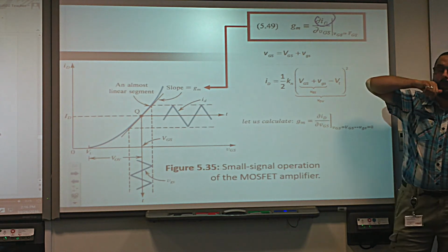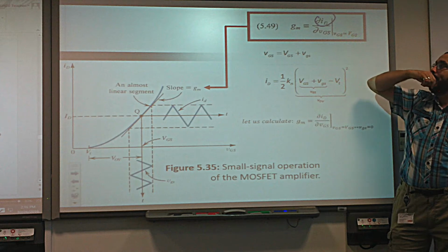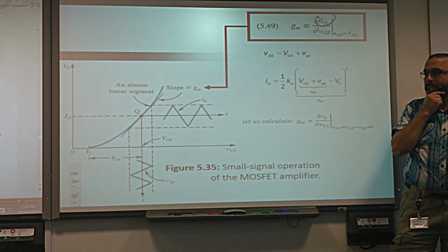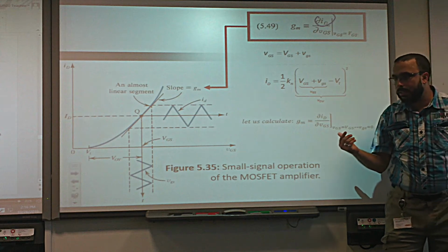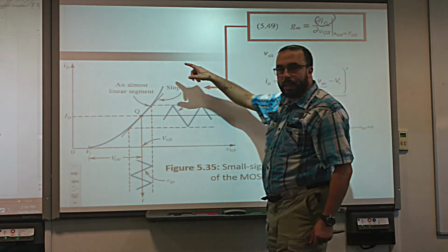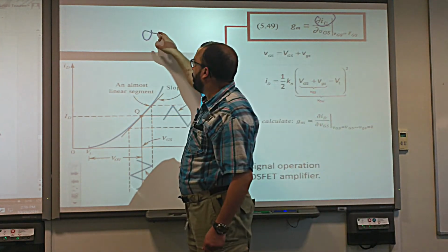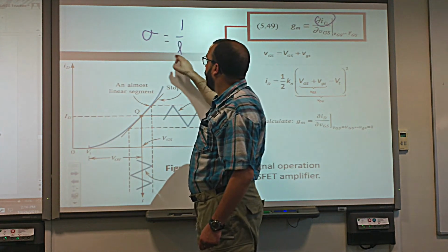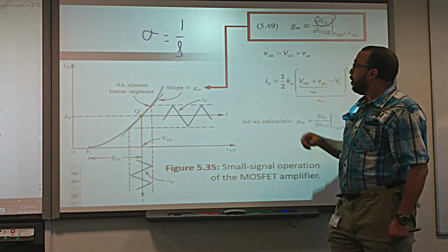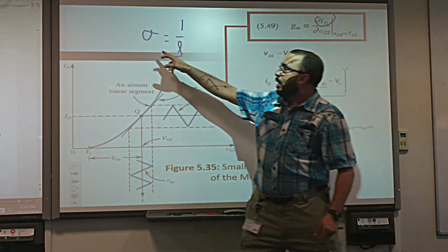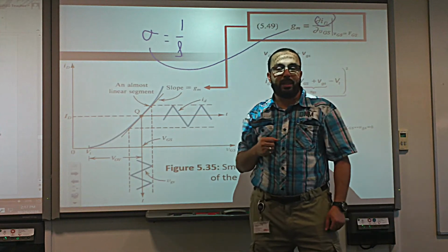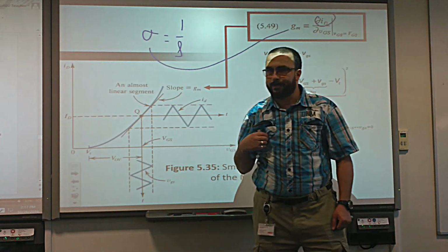by the input voltage, we are talking about AC here, we find a parameter that has the unit of conductance, meaning the inverse of resistance. Remember? The conductivity parameter sigma, if you remember, is equal to what? 1 over rho, resistivity. Very good. So this transconductance Gm has the same unit as sigma, the conductivity, and that's why we call it conductance. Okay.